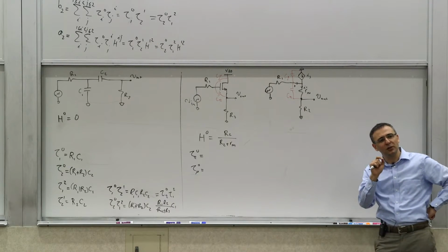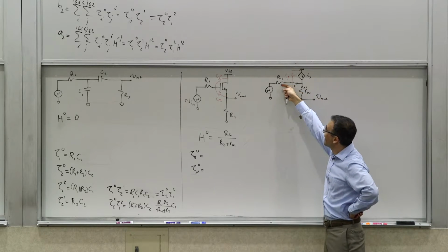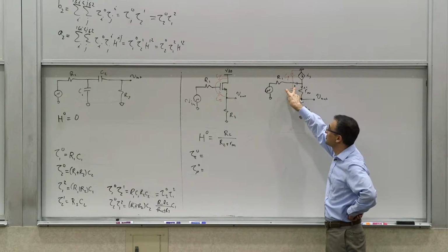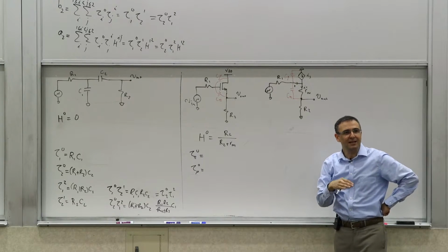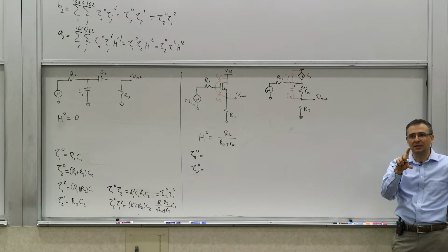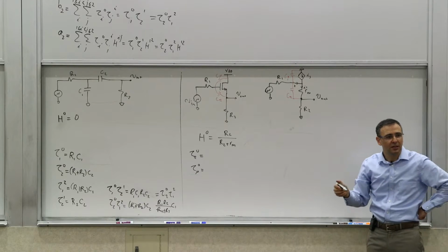We derived the general calculations for this. Because there's current flowing through here and there too. If you apply a test voltage here, it's not just the Rm. And we did calculate the general resistance seen from 3 different ports of a transistor. You remember we derived this case, it was a homework problem last quarter.